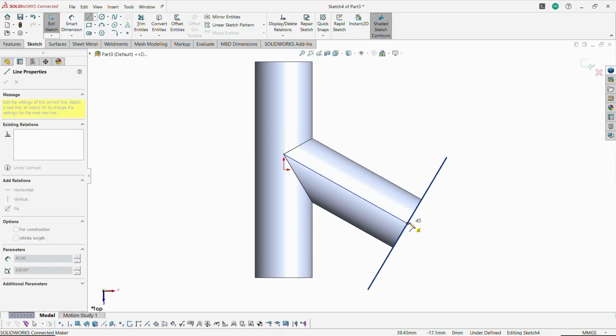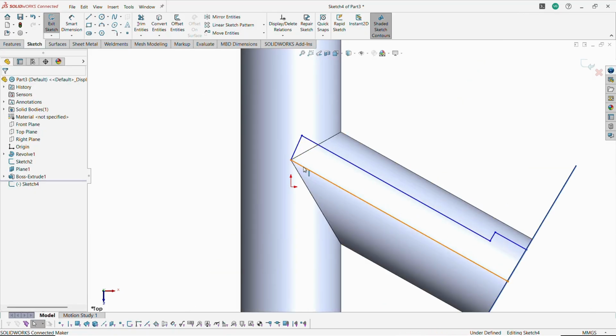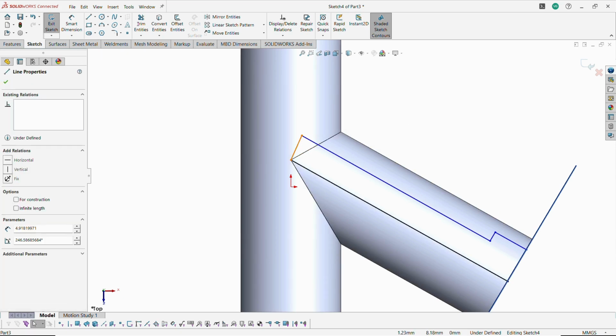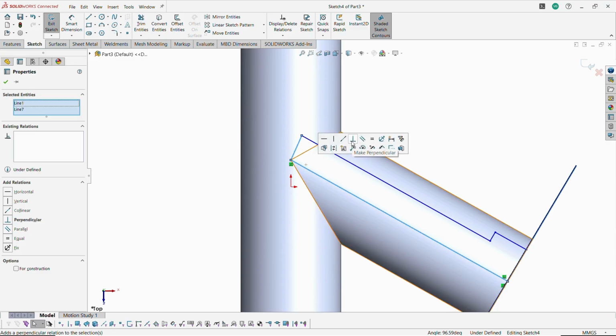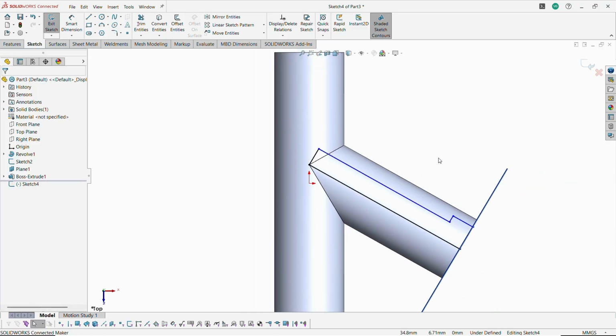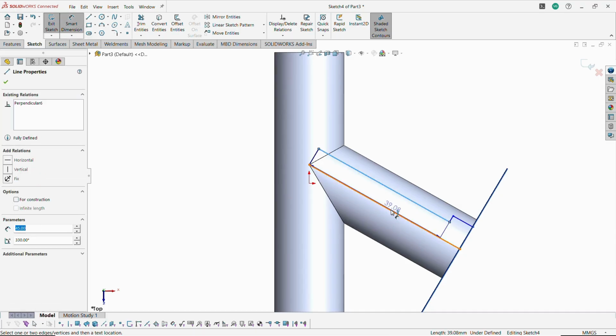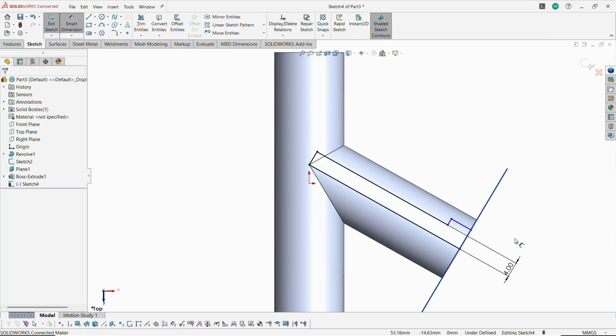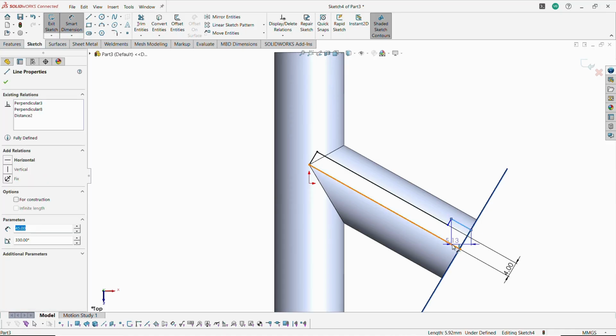Now select a top plane and create a new sketch. Draw a pocket profile. Draw an angular line and create a complete counterbore profile formation. Once it is created, choose this vertical line as well as an angular line which is a fixed one. Then use a Perpendicular constraint to fix this particular line. Afterwards, using Smart Dimension to fix this point, select the line as well as this line profile. What is the dimension for this? It is 4 mm. Now choose this and the line profiles.